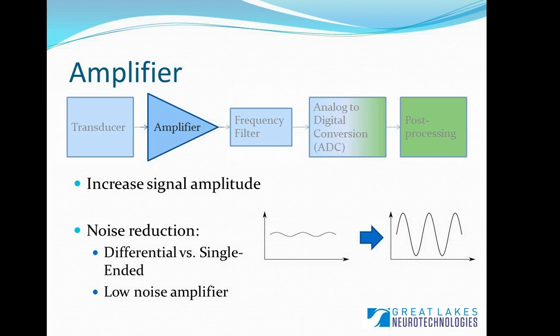So what this means is if you have 2 electrodes on the arm, and because of constraints of your biomedical system, you need to place the amplifier and the rest of the data acquisition device elsewhere, the wires connecting between the data acquisition device and the transducer will pick up noise, but because they're running along a similar path, should pick up similar noise.